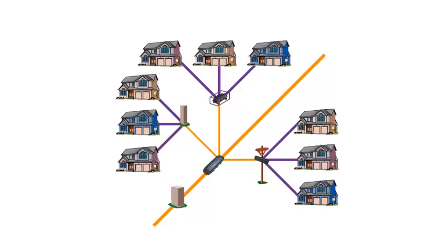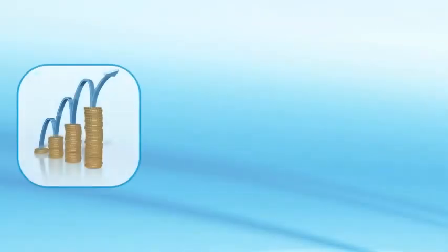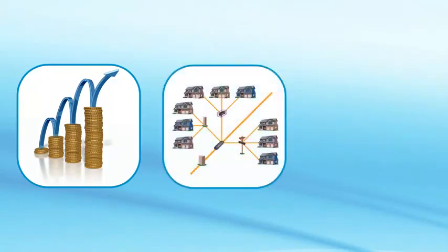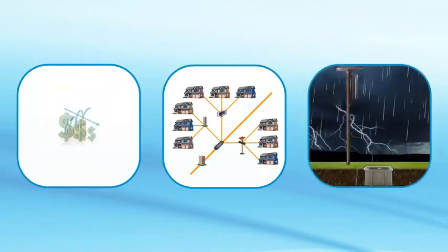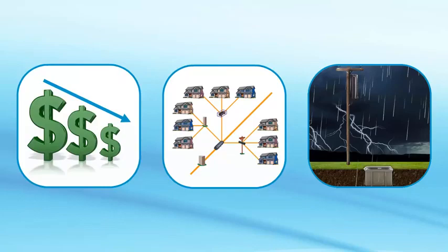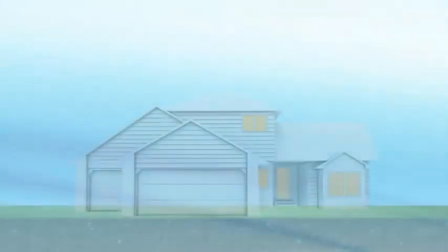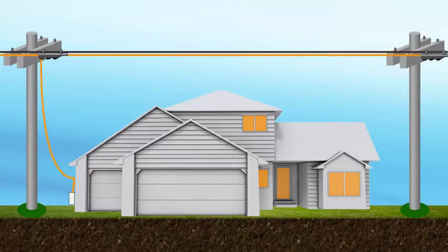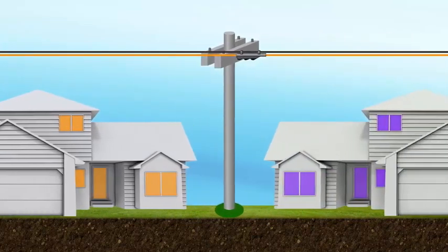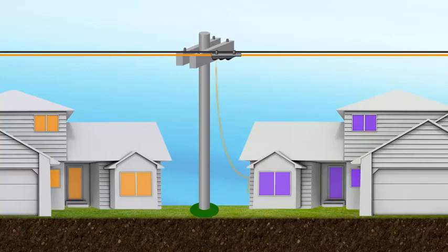at the subscriber's residence. Despite additional costs associated with adding connectors to fiber access terminals, the savings in cable placement, and the elimination of the need for splicing in sometimes difficult weather conditions on a pole or at a wall more than offset the added expense of the hardened connector system. Connectorized solutions also help offset upfront deployments where installing the drop to the premises can often be deferred until service is requested.